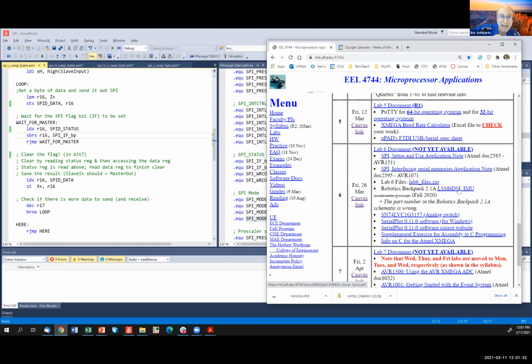You're going to send the address of the control register, and then you're going to send the data to that control register. Once you have it all set up, then you're going to read the data, and the data will be the X, Y, and Z acceleration. And you'll display this somehow. Probably, I think we have you using your UART to display those values.